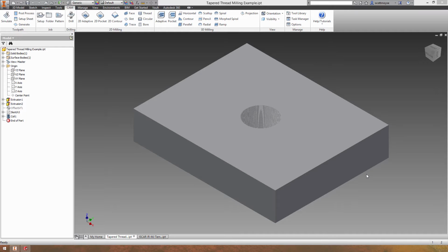My background for the last decade has been woodworking, so I've kind of lost touch with threads and the engineering side of things. But a customer on site while I was doing a demo asked if HSM was capable of machining a custom thread using a single tipped 3-pointed disposable blade and a boring bar. He wanted to machine a thread right to the bottom of a hole, and he couldn't use a tapping tool because they extend too far beneath the hole. So in some cases, it was impossible to program those types of threads on his CNC machine.